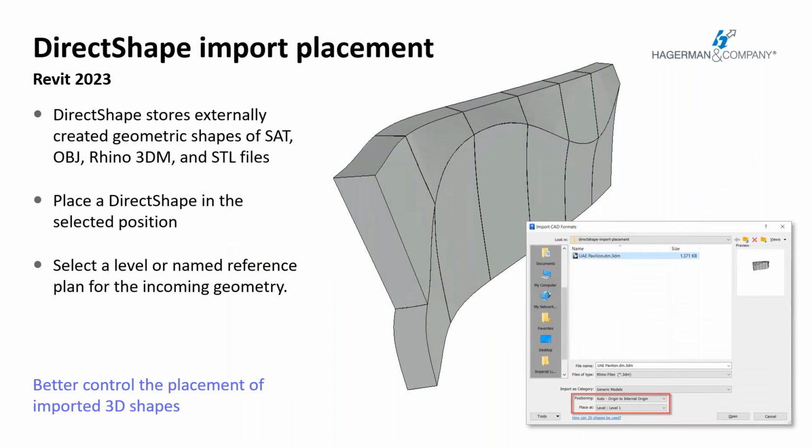And then DirectShape is a Revit element that stores externally created geometry shapes of SAT, OBJ, Rhino 3DM, and STL files. So there were some improvements here. You can use it to interpret closed solids or meshes where there's not information available to create a real Revit element. They've made it easier to define the placement with auto origin to internal origin or manual. You can also select a level or a named reference plane.